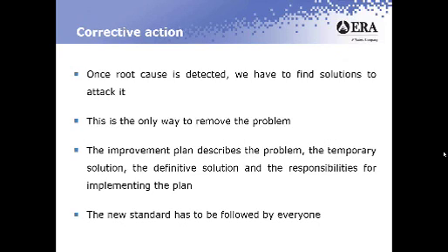Your error proofing is trying to put something in place that will definitely prevent that mistake, that error, that issue, that problem from reoccurring. At the same time, you have to correct it. If it's a major issue, you need to put something in place to correct it immediately. Preventive would be looking at, what can I do? Can I minimize some of the manual processes by automating it? Can I use my IT? Can I use our systems? Can I do something of that nature that actually helps in preventing that error?